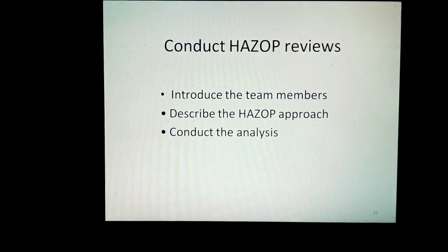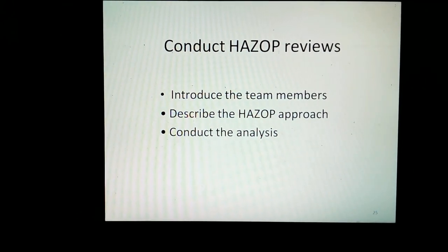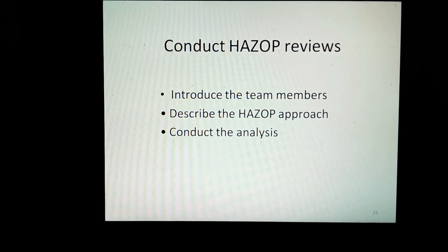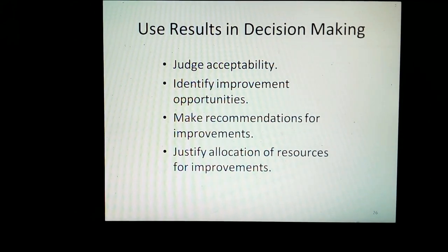Conduct HAZOP reviews. Introduce the team members. Describe the HAZOP approach. Conduct the analysis. Use the results in decision-making. The report. Judge acceptability. Identify improvement opportunities. Make recommendations for improvement. Justify allocation of resources for improvement.